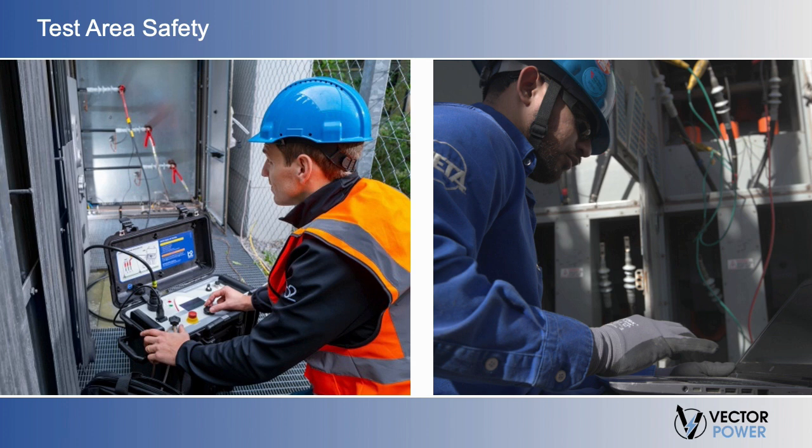If testing cables or sections of bus run, electrical shock approach boundaries must be established at both ends of the cable or bus run to create a safe test area for workers. Also, an energized cable can create capacitive coupling to adjacent cable phases. To prevent capacitive coupling, cable phases that are not energized or tested must be grounded.